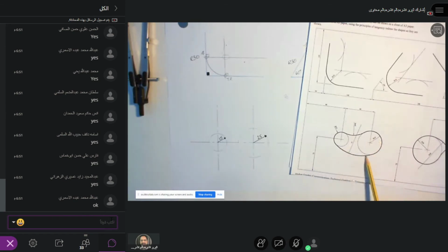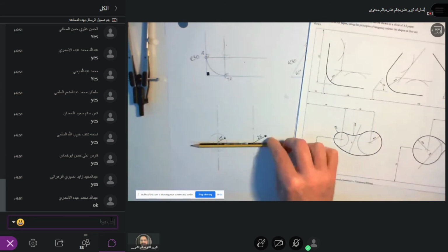The radius of this bottom curve, you can't see it very well on here, but it's 75 millimeters. The radius of the small, slightly less deep belt on the top is 40 millimeters. So what do I know about these two circles? The only thing I know is the radius is 15 on this one, and on this one the radius is 25. The other key point I know is where the centres are. The centres are fixed. It's very difficult to see on the camera, but it's 60 millimeters between these centres, and they're horizontal.